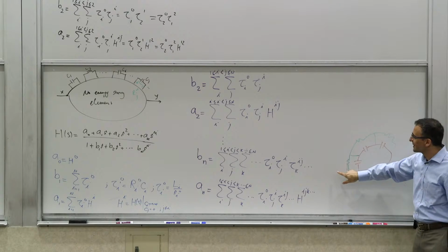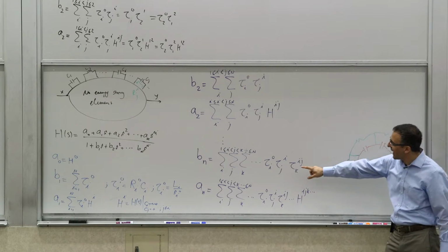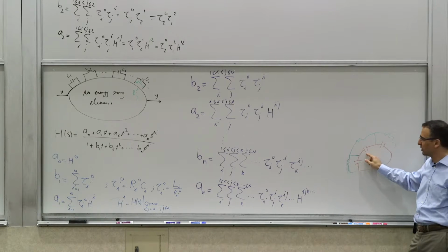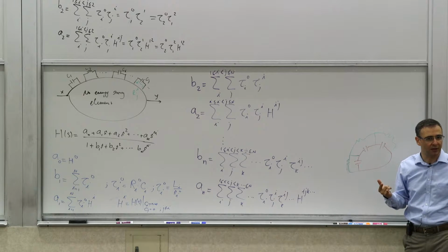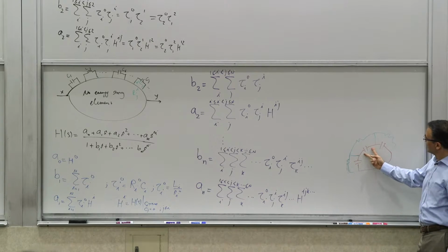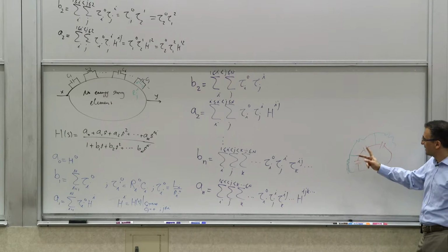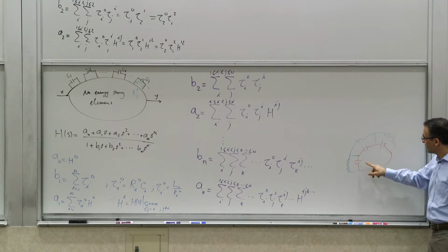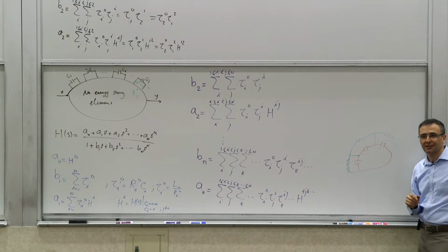So think about the time constants, these time constants. So if I have the tau 1, 0, tau 1, 0 is going to be non-zero, right? So you have some resistance. These are going to be open circuited. You will see some resistance here and some resistance there, so you get some finite value of resistance, some non-zero value, right? Now, tau Ji, what is the time constant you see across here when this guy is shorted? That guy is shorted, this is still open, that's not a problem, right? But now let's look at the tau 1, 2, 3. If you have, this is 1, this is 2, this is 3. The resistance you see across here, if 2 and 3 are shorted, is what? 0. Is 0.